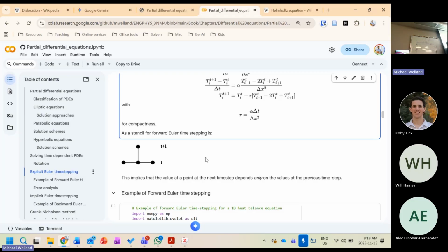You're going to use that to calculate the temperature here at your next time step. So this is your t plus 1. That plus isn't coming through the screen. This is your temperature at time t plus 1. These are the current time t, i minus 1, i plus 1, and your current one. So that's the structure of that. Two minutes here.